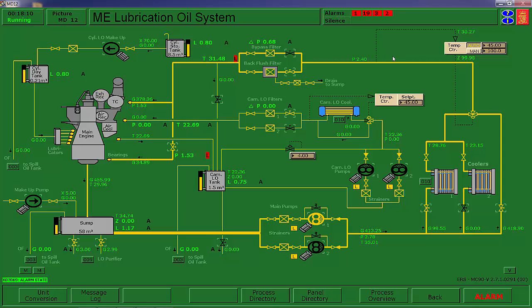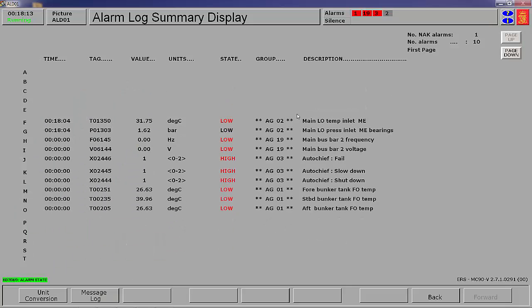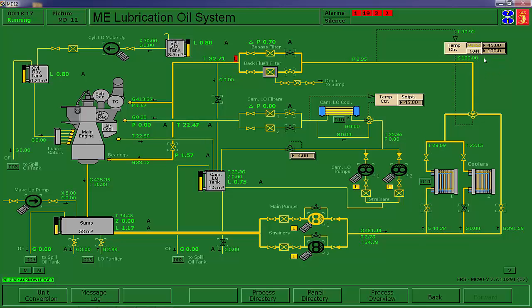That's why it is important that, let's go ahead and clear the alarm. It is important that you are controlling it manually, in automatic. And I want you to notice that this three-way valve is shifting right now, and the flow is all going towards bypass. The only thing heating this sump has been our lube oil purifier, and we don't want to lose that heat. All right, so it's being shifted over so that we're not cooling it.